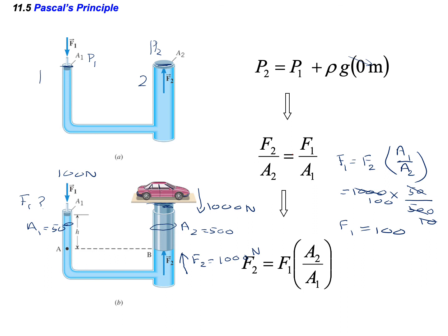So if you have the ratio of A2 to A1 like 1000 times, then you need a 1000 times smaller force. So depending on the ratio of the areas of both sides, you can reduce the applied pressure on the opposite side to do some work.